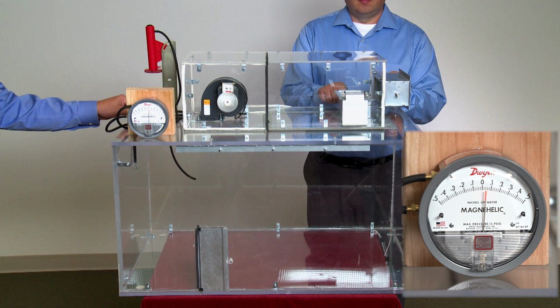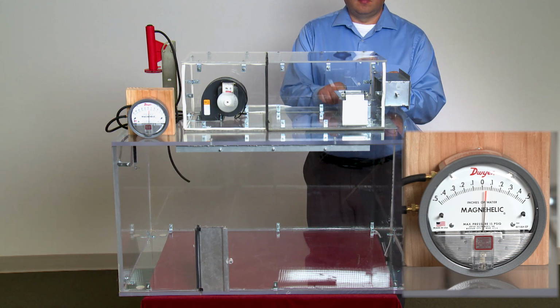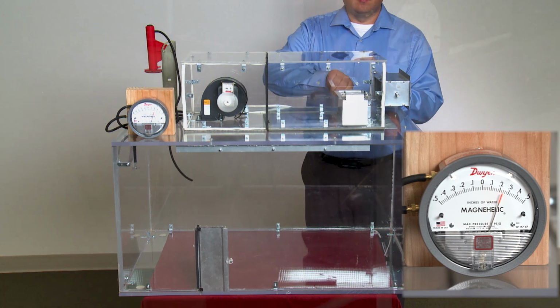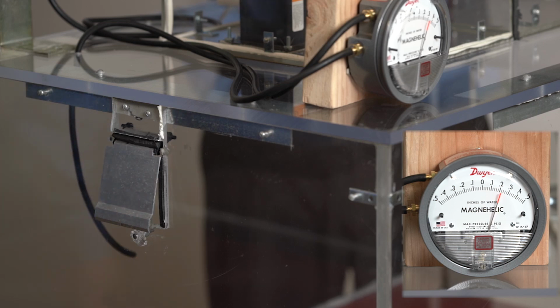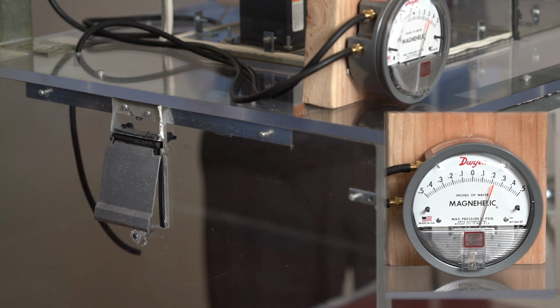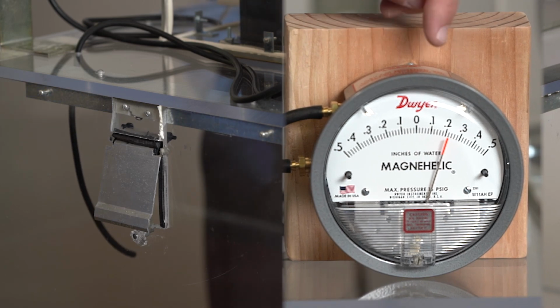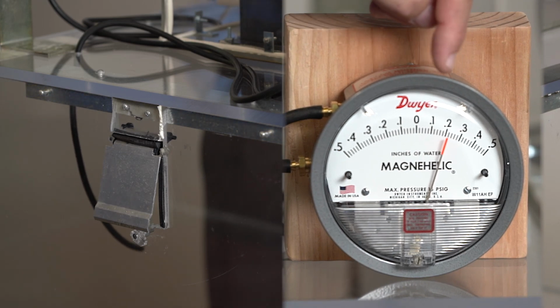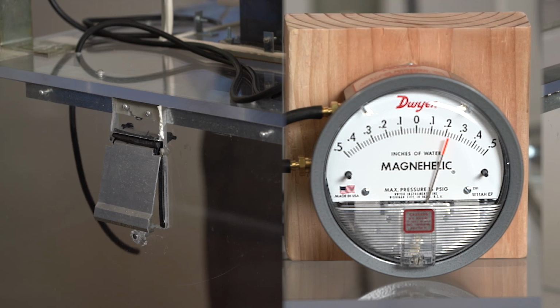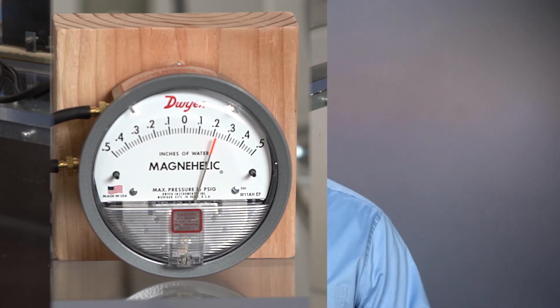But now let's go to economizer mode. Outdoor damper fully open, return damper closed. The building pressure rises further, high enough to force the barometric damper open so it now relieves the excess air. For this model, we sized and selected this damper to relieve the required CFM at 0.2 inch of pressure. With barometric relief, the building is still under a positive pressure, but not nearly as high as when we relied on only natural relief.